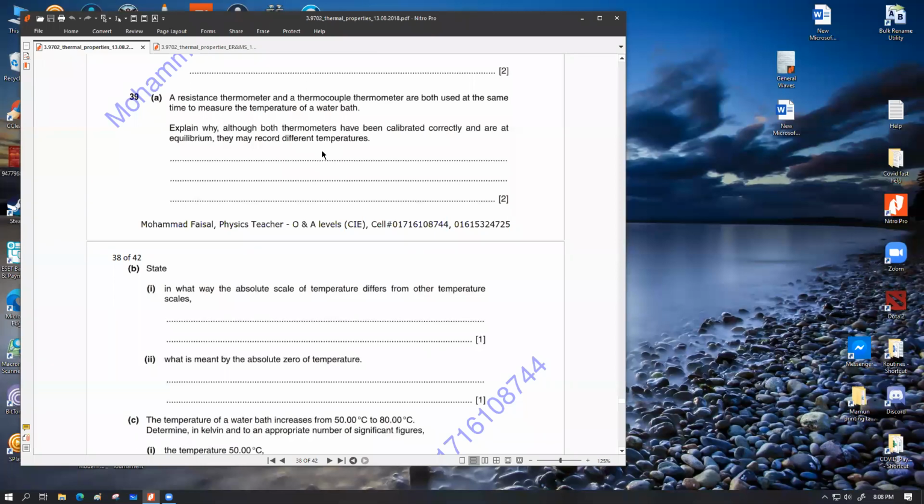So that was a very important aspect. Why am I telling you this? It is because for a liquid-in-glass thermometer like a mercury or alcohol thermometer, this is a valid property, but it is not equally applicable for a resistance thermometer or a thermocouple thermometer. Their working principle works by a curve. Now, whenever we do calibration, we don't plot each individual minute value of temperature. We take two temperatures, or let's say 4, 6, or 10 temperatures, and we develop the equation for this and draw a best fit curve.